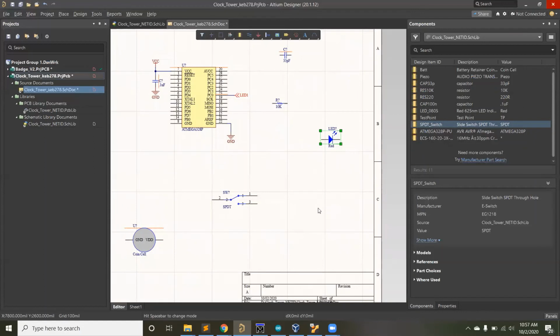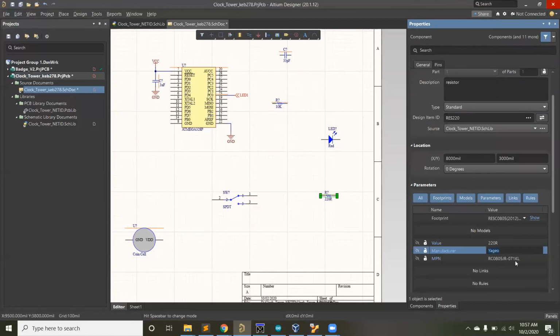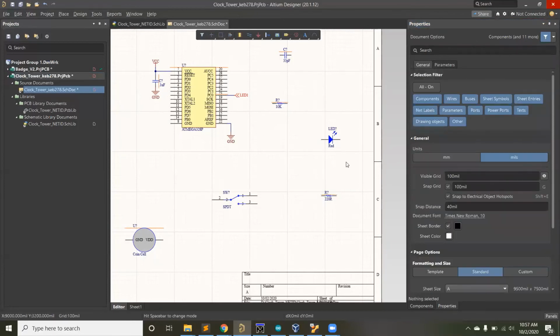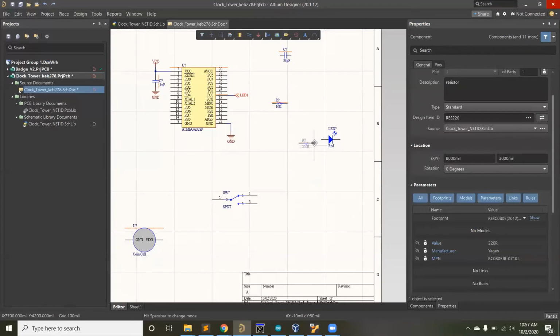The LEDs. These are one of the components on the board that are directional. So you need to connect this so that power will flow through it. You'll see on the board that I used 330 ohm resistors for that. I think you say 220, but you can make them 330 just by changing the value and the part number. You can put those in line with the LEDs.